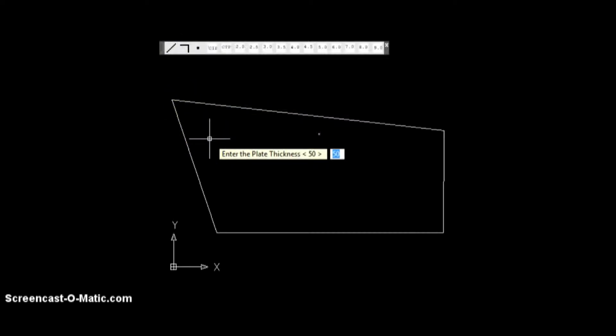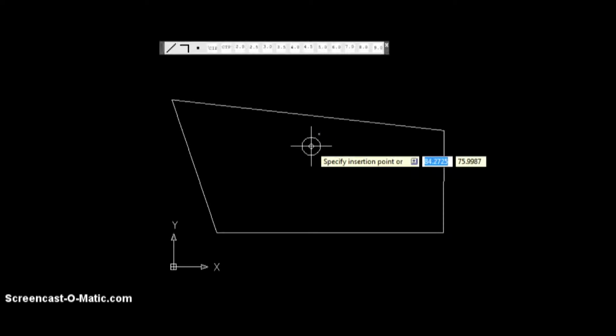As we enter the plate thickness 50 mm, enter the cutter diameter 3 mm, enter the cutter angle 5 degree, enter the bearing transition. If you want to make the transition from 3 to 5 mm bearing, the small diameter shows the 3 mm cutter and the outer diameter shows the cutter path on top of the die plate 50 mm thickness.